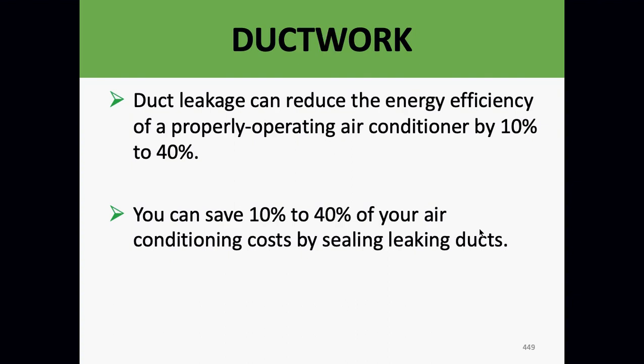Ductwork: duct leakage can greatly reduce the energy efficiency. Ducts have to be sealed. You can save 10 to 40% of your air conditioning costs by sealing leaking ductwork. It's important to go up into an attic occasionally and look. If the ductwork has been in there forever and you've never gone up there while the air conditioning is running, run your air conditioning on a nice warm summer day, go up there and look for the cold spots. You might be surprised. You've got to seal ductwork.